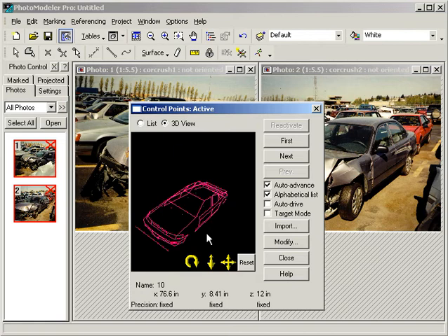You then import the 2 unknown photographs and assign them an inverse camera. With the images imported, you can then reference the fixed points to matching points on the crushed vehicle photos. When you process, inverse camera will use these fixed points to solve for camera parameters. Further details on this method can be found in the help file. In this tutorial, we will use the control point file import method as it is more flexible.